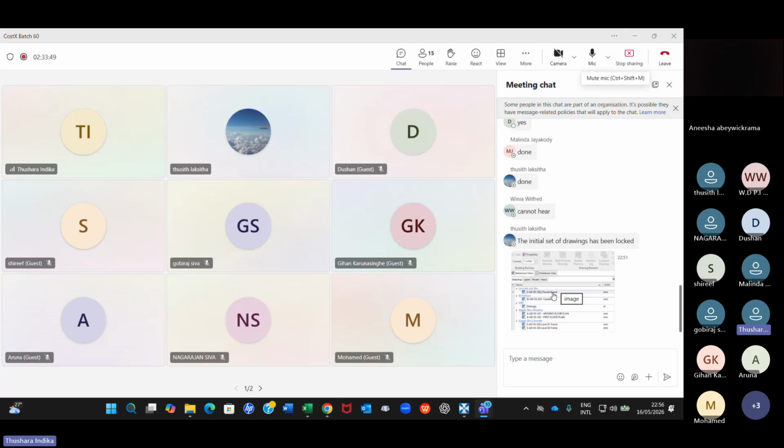Now, when you do the revisioning function, that means you have received a particular drawing, let's say the foundation layout revision. First you introduce a revision like this, then everything will be locked. Then you promote the drawing, meaning you are introducing, you are adding the revised drawing. Then what you do is you compare the two drawings.